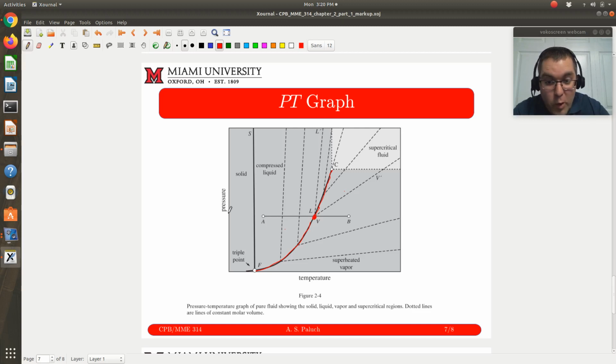Or equivalently, if you're given a pressure and told you're at two-phase coexistence, I would just draw an isobar to where I find myself on my coexistence curve, and that would pin down the corresponding temperature.